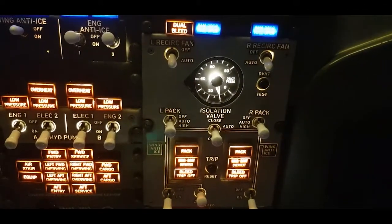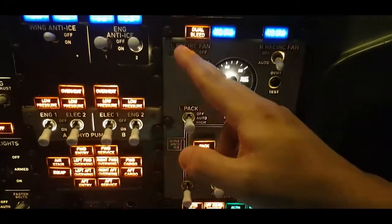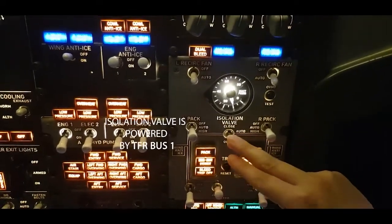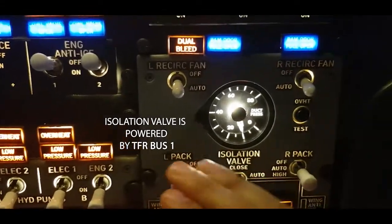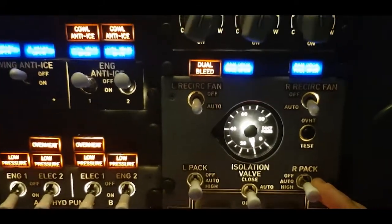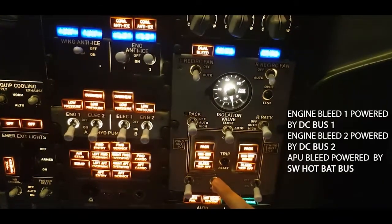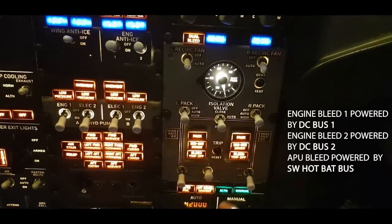Okay, so guys, let's talk about the bleed air system. And here we have the bleed air panel with the lights. If we talk about the isolation valve, it's this one here. It separates the left side and the right side of the bleed air system. The engine and APU bleed air valves control the air that goes to the bleed air system. Here we can see the engine bleed 1 and number 2.